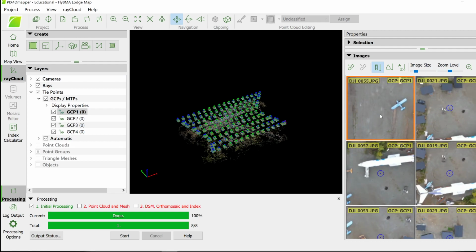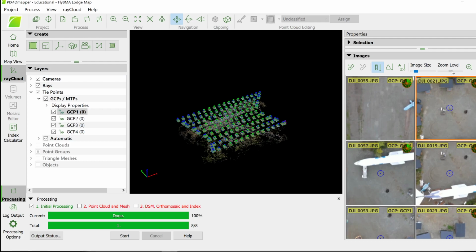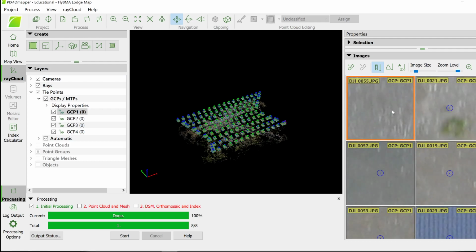You can see there's a number 1 that I spray painted for this project. Now, in the previous module and the documents that I asked you guys to read, I did specifically say that we would use proper GCP markers for the project. But in this case, just to make sure it's clear that it's number 1, number 2, number 3, number 4 GCPs, I spray painted it, and then I used an edge of the number that I spray painted as the marker for the RTK. So in this case, I'm going to click right here. That's where we used the RTK module.